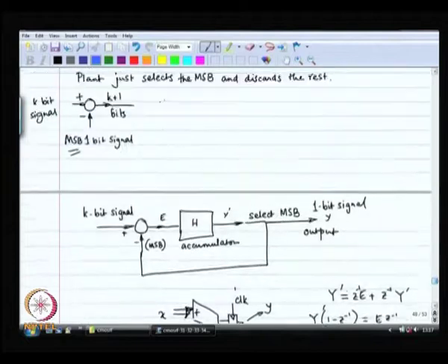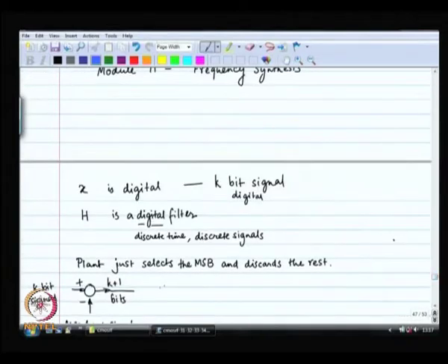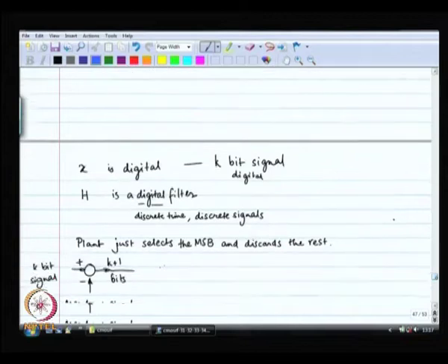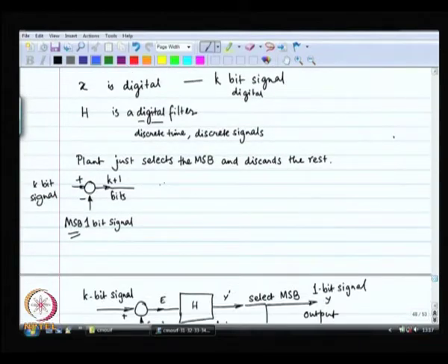modulators from our A to D converter book and we modified it a little bit, because we are not really doing analog to digital conversion, we already have a digital number, we are going to create a 1-bit digital number whose average represents the original digital number. However, I want to make sure that that 1-bit digital number is not a periodic signal, that was our necessity, right, and that is what we suited our sigma delta modulator for.